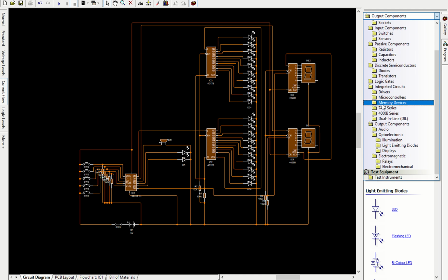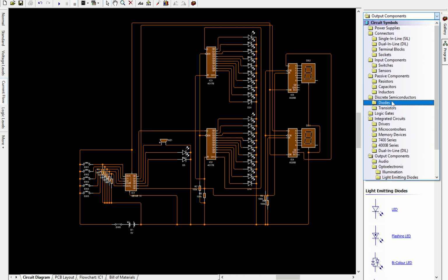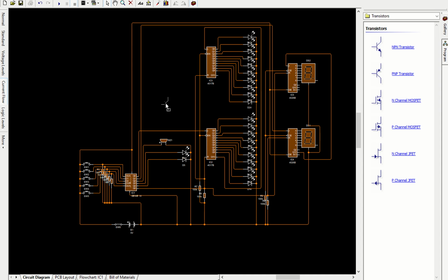The idea with a transistor is an electrical switch, and so it's got a collector and an emitter, and in the middle it's got a base. Well, two types actually. It turns the transistor on or off by a voltage or current being applied to the base. You connect that middle leg to the genie, and when that goes high, that allows electricity to flow through it if it's an NPN transistor, or if it's a PNP transistor, it's always on, and when you put electricity on that leg, it then turns itself off.